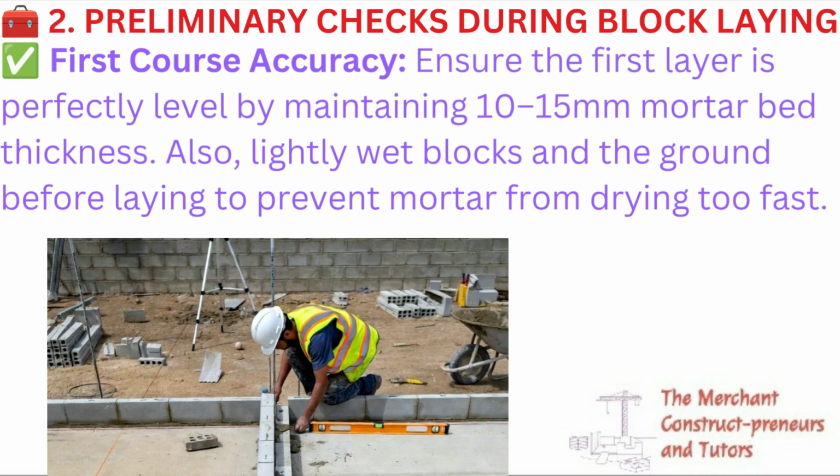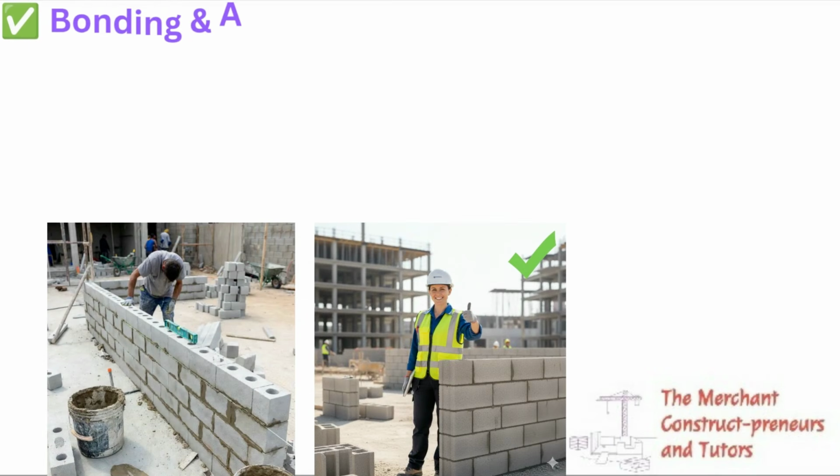One thing that most people fail to do is wetting the ground and also the block while trying to lay the first course, because these two elements are already dry. The only wet thing among them now is the mortar. And once you lay your mortar on the floor, it sucks it out. So you need to ensure that it is clean.